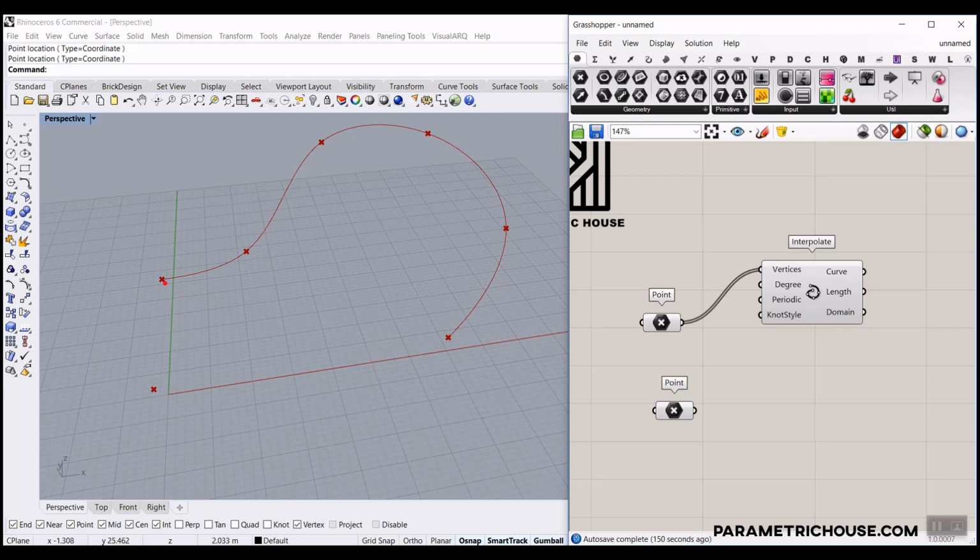Okay, now we have to play with some of these points here to make the building. First of all, we have to use these two points to make the third point. Let me just put it as blue, and that's using the xy of this. That's going to be the x and y of this point and the z of this point, right? We'll make this point. That is the reason we want to connect them together to make this closed surface for the windows.